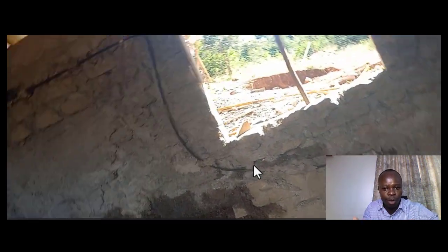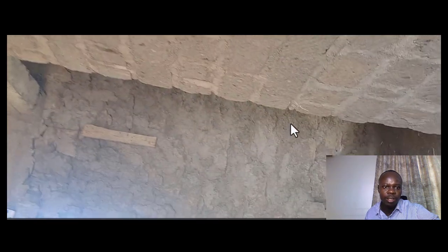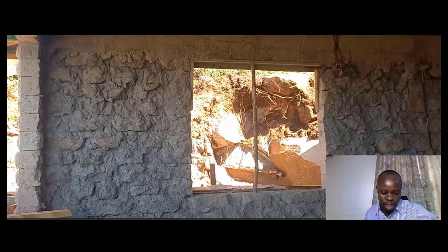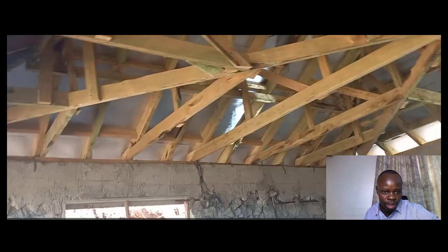After walls, you also have the ceiling. In this case, these are just trusses, but then you will do brandering, and then you install gypsum. For instance, this is intended to be a gypsum finish. Once you've installed the gypsum for the ceiling finish, you measure that paintwork in that case.